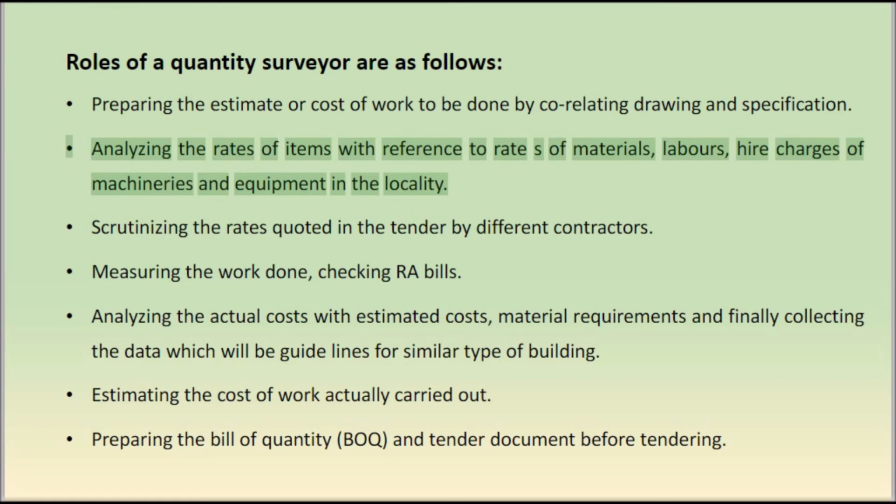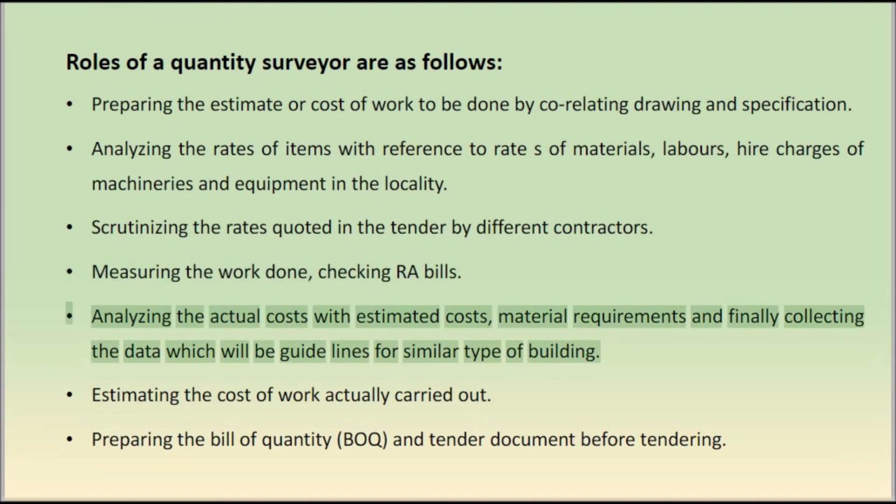Scrutinizing the rates quoted in the tender by different contractors. Measuring the work done, checking RA bills. Analyzing the actual costs with estimated costs, material requirements, and finally collecting the data which will be guidelines for similar type of building.